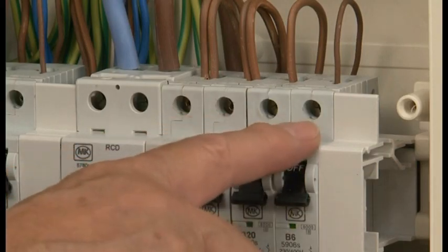The item, connection of single pole devices for protection or switching in line conductors only, is a visual check to verify that all single pole switching and control devices are connected in the line conductor only. Don't forget that this check is an addition and not an alternative to the required polarity tests.